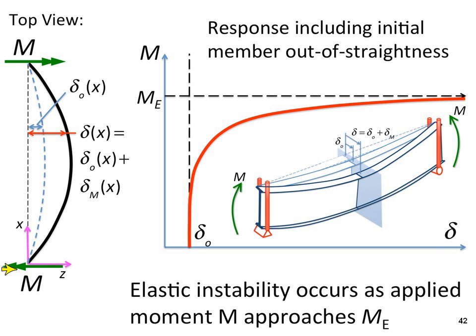I've got the moment applied at one end, the equal and opposite moment applied on the other end, and then I've got an initial imperfection. So I could use anything, maybe a sine curve or something like that. So let's say this is the top flange, and it's got a small initial imperfection. It's going to be small, maybe even just the unbraced length divided by 1,000, some small amount. But then as I start applying these moments, that small imperfection is starting to grow.